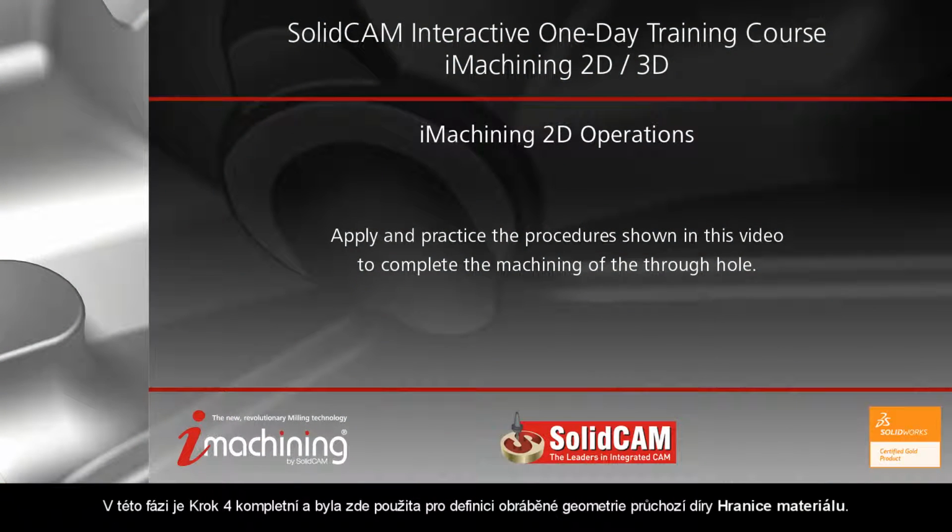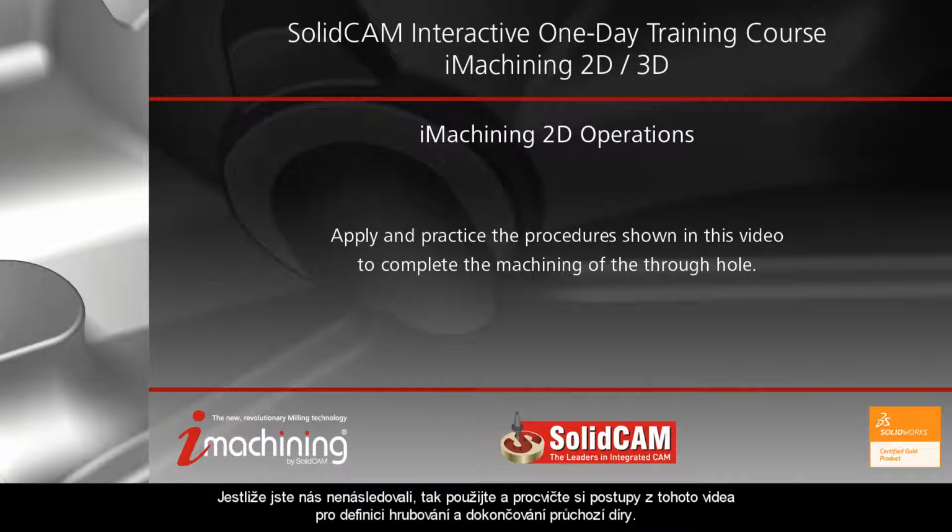At this stage, Step 4 is complete and a material boundary was used to define the machining geometry for the through hole. If you have not followed along, apply and practice the procedure shown in this video to define the rough and finish machining of the through hole.